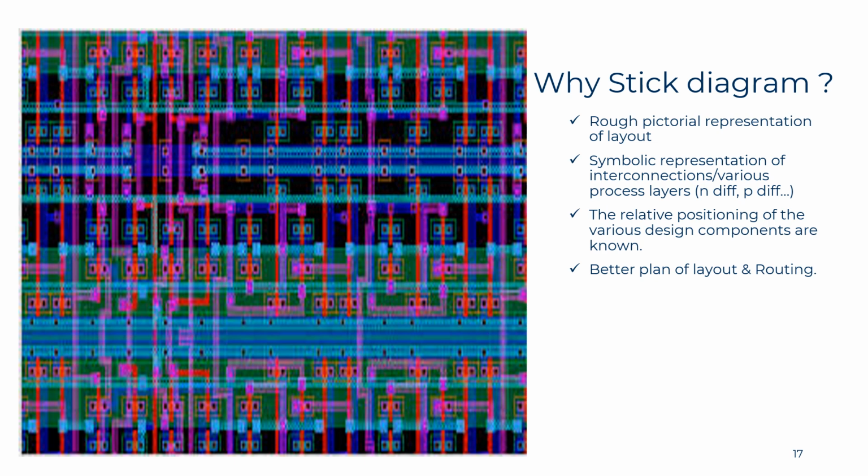So what does it have to do with the layout? If a layout is properly and efficiently done, you will have minimum area, minimum delay and minimum power. It depends on the length of the wires used and the positioning of the blocks or the components. If you have not properly placed the metal layers, there may be capacitance forming between the layers. Not only metal layers, between the layers there may be unnecessary parasitics, that is resistance, capacitance and inductance being formed, which will lead to delay, more power consumption, and the area also will be larger if you use improper routing.